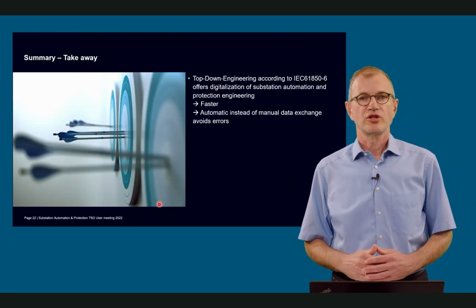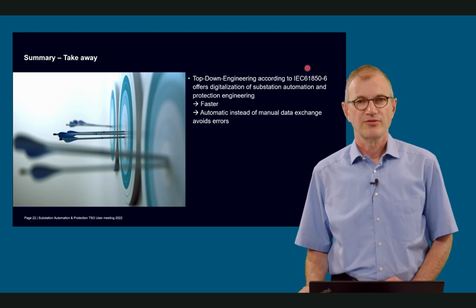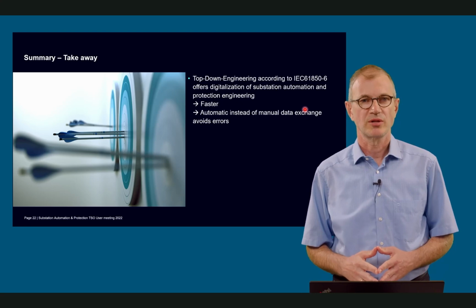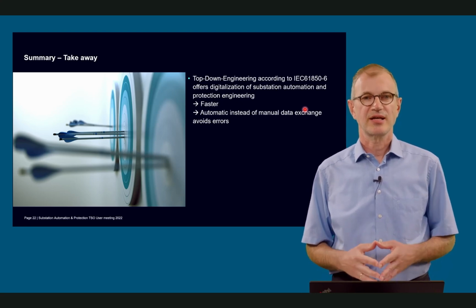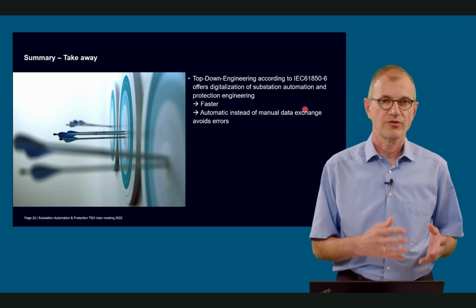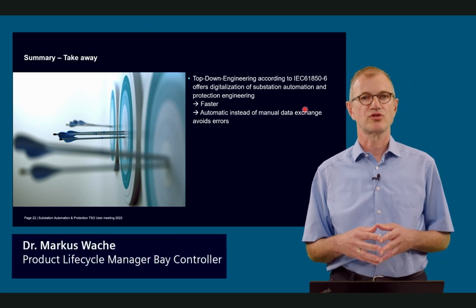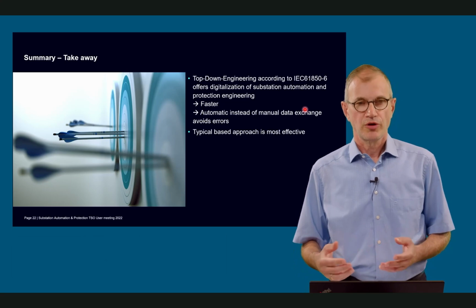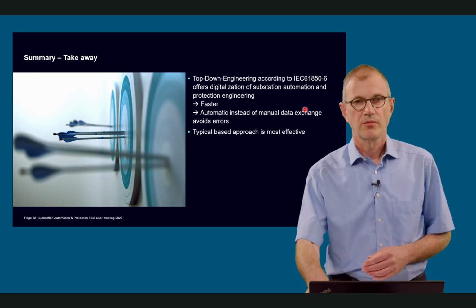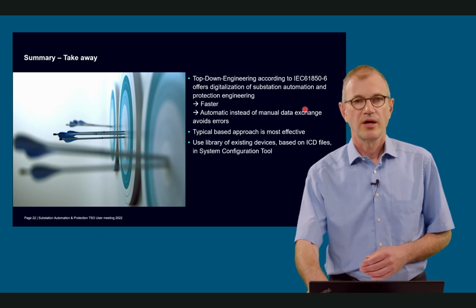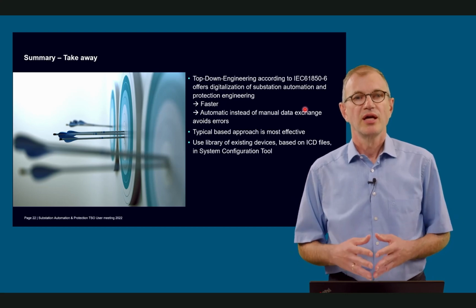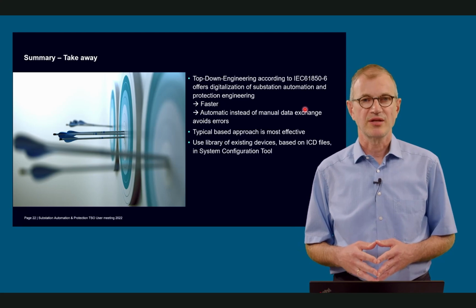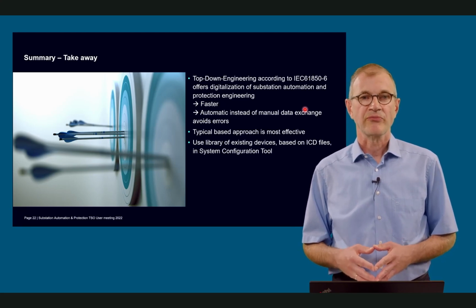So this top-down engineering, according to 61850-6, offers digitalization of substation automation and protection engineering. It's faster and it's automatic instead of having manual data exchange. That, of course, avoids errors. Template-based approach is most effective, but I think you do that anyway. And a hint from the manufacturer side: use a library of existing devices based on ICD files in the system configuration tools.